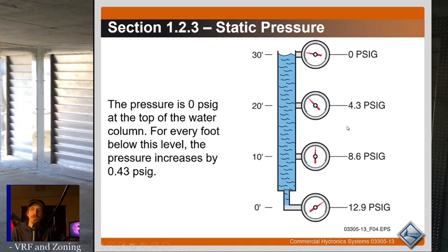It's going to be pretty rare in most residential and light commercial situations that you're dealing with more than 3 stories above the boiler, right? The boiler's in the basement, has to go up to the first floor, up to the second floor, and then we still have all the way to the top of the second floor to work with. So most boiler systems are set at 12 psi, because that ensures that we've got water filled up all the way to the top of the system.